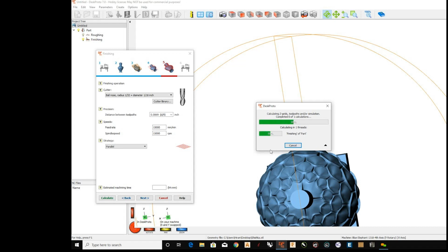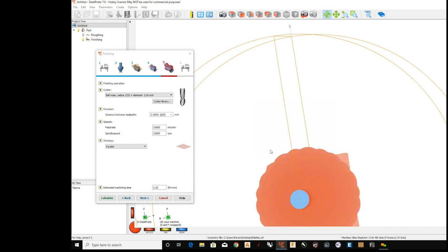I can actually use the Mach 3 extension, because Mach 3 uses .txt, .tap, .nc. My controller reads the same thing, but I haven't tried a Mach 3 post on it. I use .mmg, .tap, .nc, and ISO.